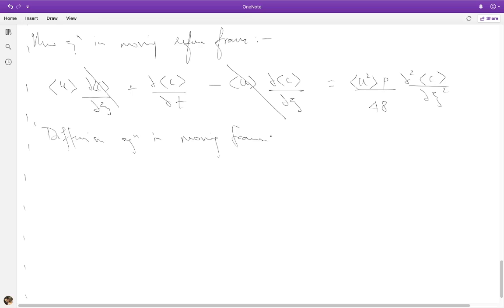If I move with the average concentration, what this tells me is that if I insert a slug of solute into a pipe, and then I move my camera, or my measurement device, along the tube with the average velocity of the flow, what I will see is that the initial slug is going to follow just the simple diffusion equation I have here. The cross-section average concentration is going to follow the following diffusion equation.